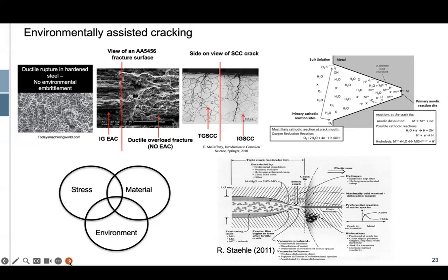We have an internal anodic reaction happening inside the crack, and an external cathodic reaction, and it is a competition between crack growth and passivation, where the passive film is broken. There are a lot of things going on here. We'll discuss in detail what is happening in the material microstructure, how dislocations and other defects are being generated and retracted, and how this cracking is propagating.